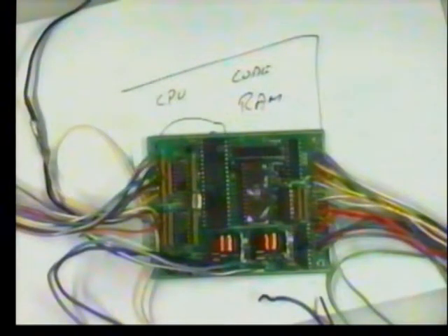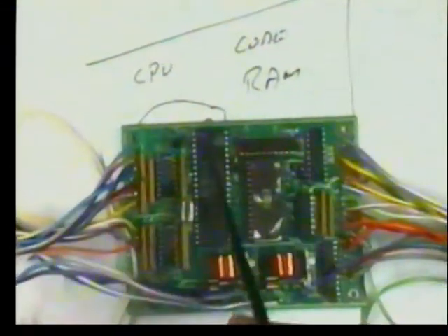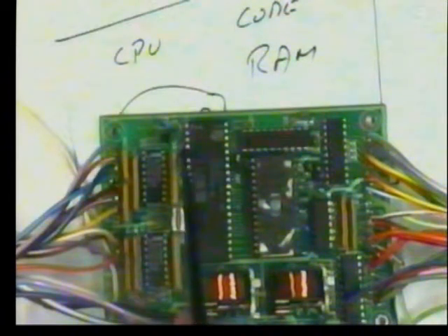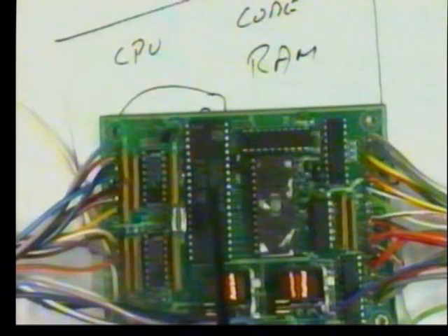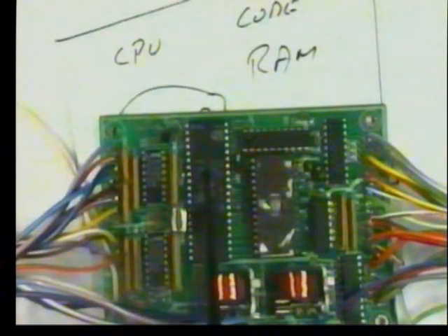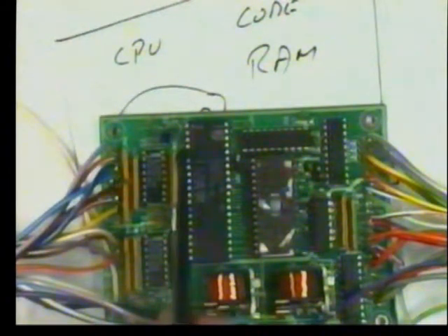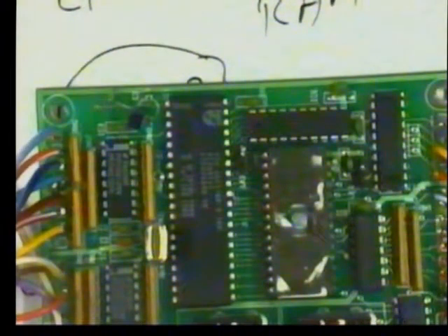The engine management unit of this vehicle, here we have inputs coming into the board. This processor, in fact 24 of the 40 pins, are memory mapped I/O that can be accessed directly by the CPU, so that we can put voltages onto these input pins and read them directly into our program.